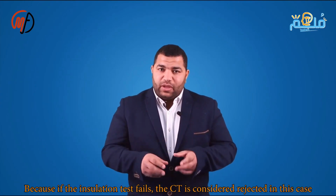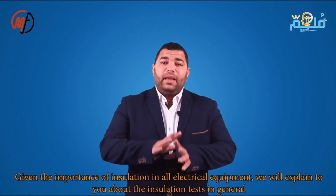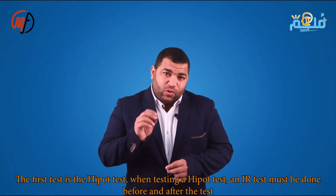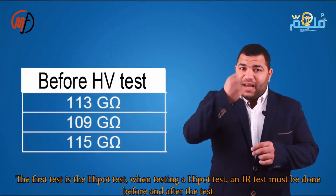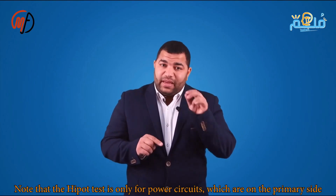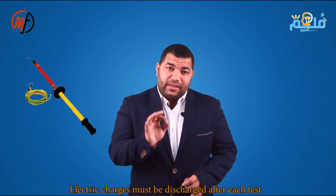Insulation is crucial, so we conduct insulation resistance tests, starting with the hypot test. Before and after the hypot test, perform the IR test. The hypot test is for the power circuit, meaning everything on the primary side, and you must discharge any charges after conducting each test.